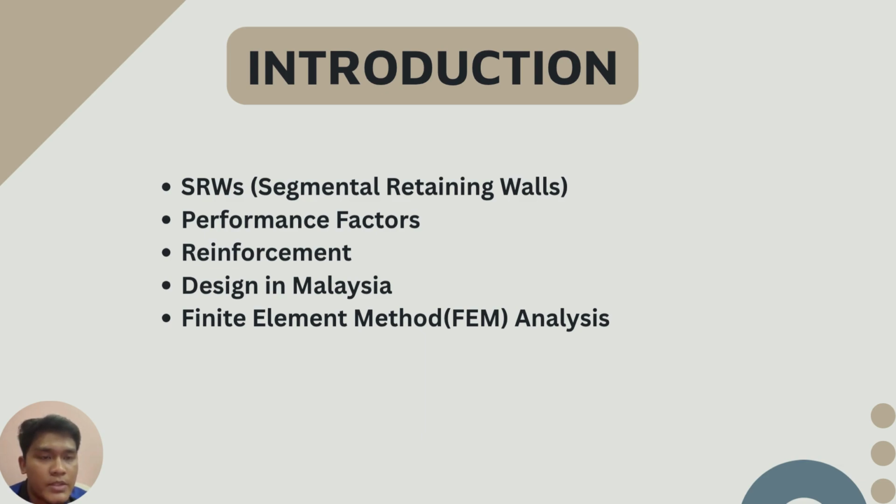To address this limitation, finite element method analysis using software like PLAXIS 2D or 3D provides a more detailed view of soil structure interaction. This analysis is increasingly used for verifying design in transportation infrastructure projects, as it can measure global stability, horizontal deflection, and settlement.